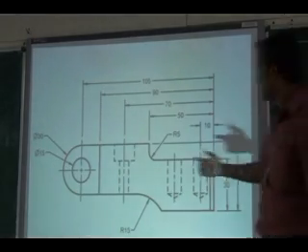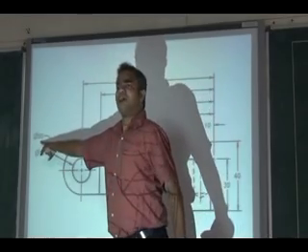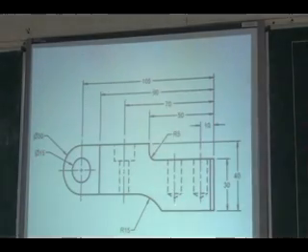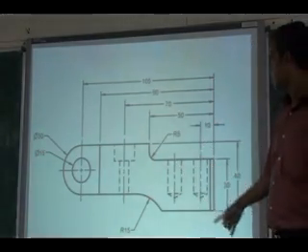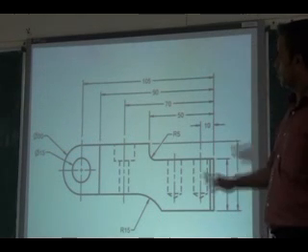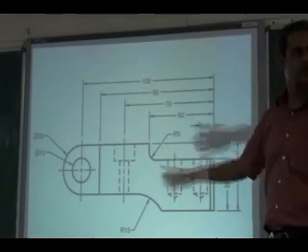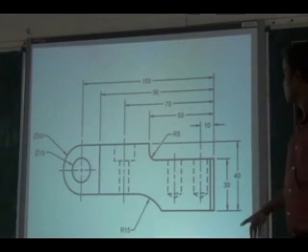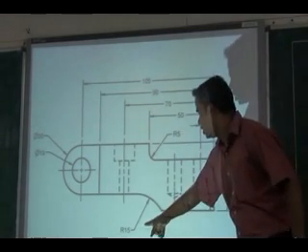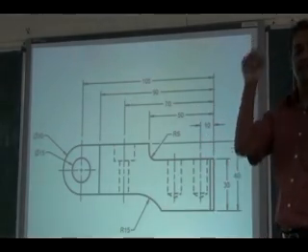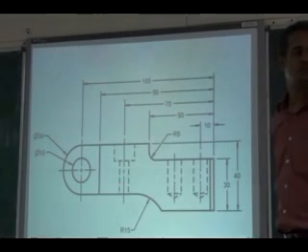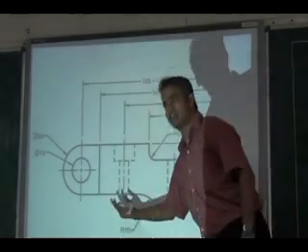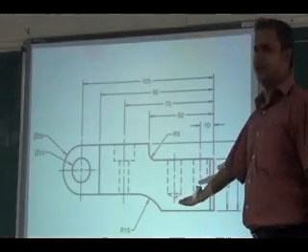Sir, the arc is shown in diameter. As I told, it should be in radius. That is the wrong one. So for the arc, the value should be written on that line. So that is diameter. It should come from the center. I should show the center, and from the center I should get it. Then it should be written on the horizontal line. So this is one procedure I can show you.